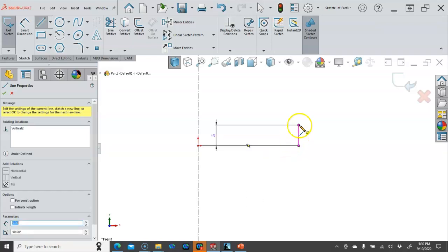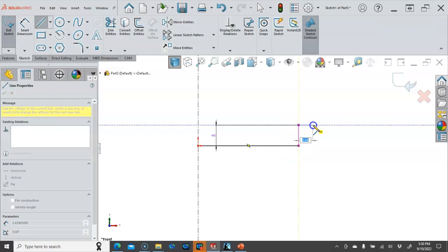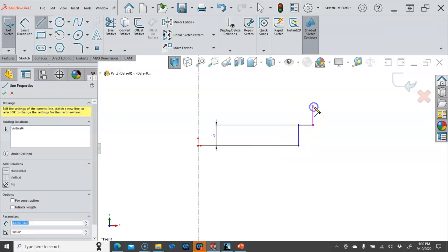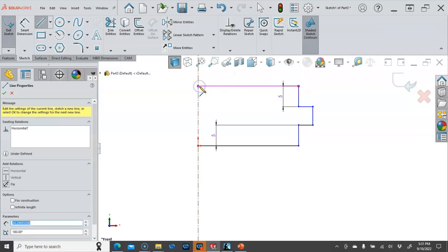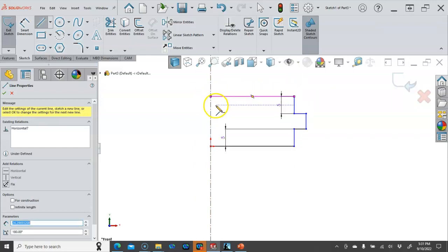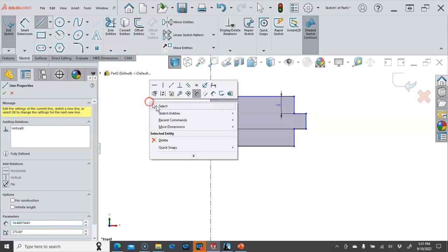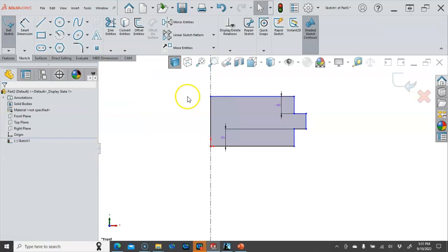Oh, okay, yeah, it scaled a little bit unexpectedly. All right, gonna bypass those and then go 5 and bring it back to the center line. And when I'm at the center line, if I don't close this off, it's going to ask me to close it off, or it's going to try to make it a thin feature. We don't want the thin features.